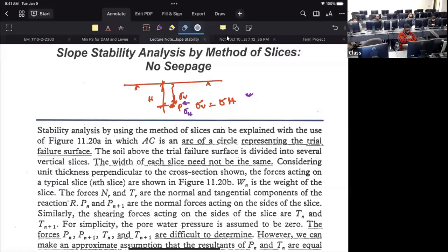Anyway, so let's go back to what we are discussing. You have a sigma v and sigma h, right? The connecting factor between sigma v and sigma h is just a factor. We call it the earth pressure factor. We name it K. K can be in different conditions, different times. It can be K naught, Ka, Kp, active pressure, passive pressure, all these things.